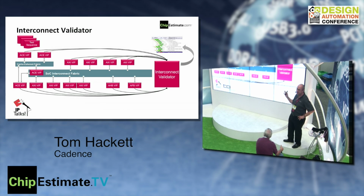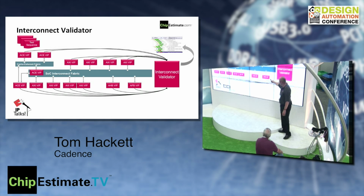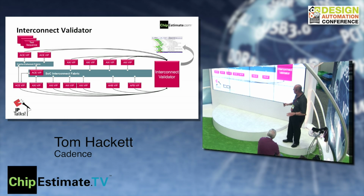And not only that, these networks can get pretty sophisticated, where data might leave the processor subsystem as, say, one 32-bit word, but end up over here as two 16-bit words back to back. Okay? So the Interconnect Validator monitors to make sure that that's happening correctly in accordance with the protocol rules. There might also be some arbitration that comes into play. You know, are things serviced in the right priority? So Interconnect Validator checks that as well.